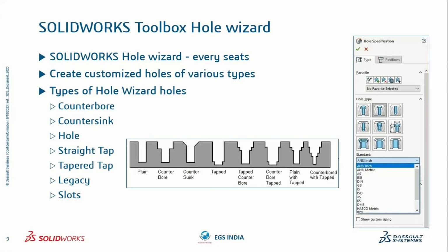And then the SolidWorks Hole Wizard. It comes in every seat of SolidWorks, like the Standard, Professional, and Premium versions. It also has standards and various hole types for use in our design process, like counterbore, countersink, and straight tap slots. These are all preloaded in our Hole Wizard.